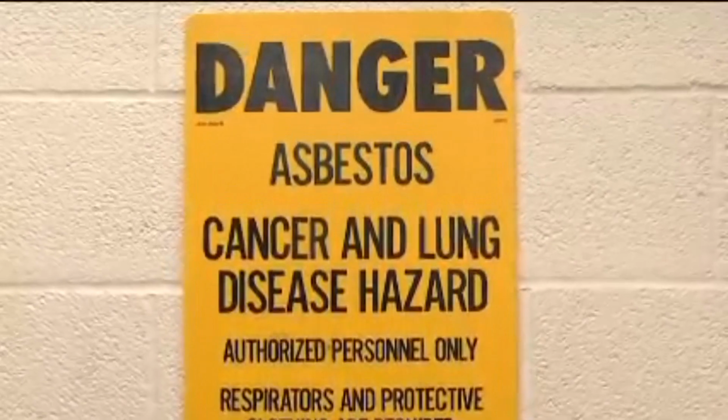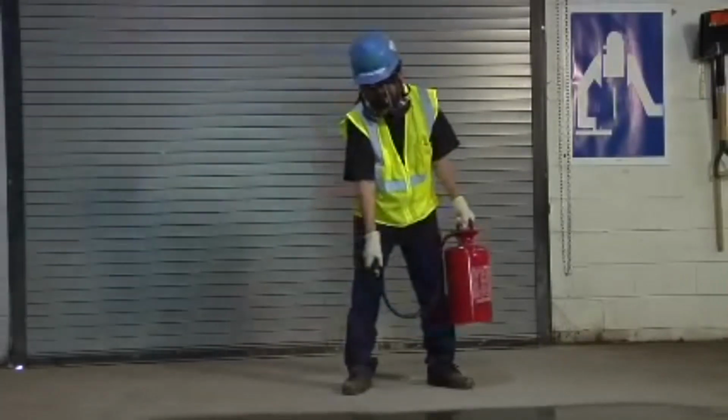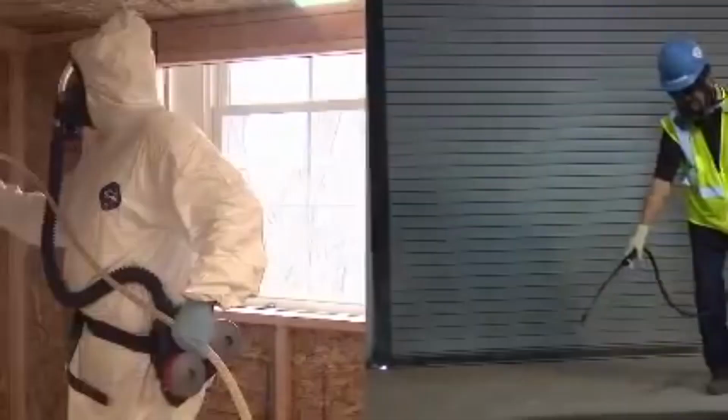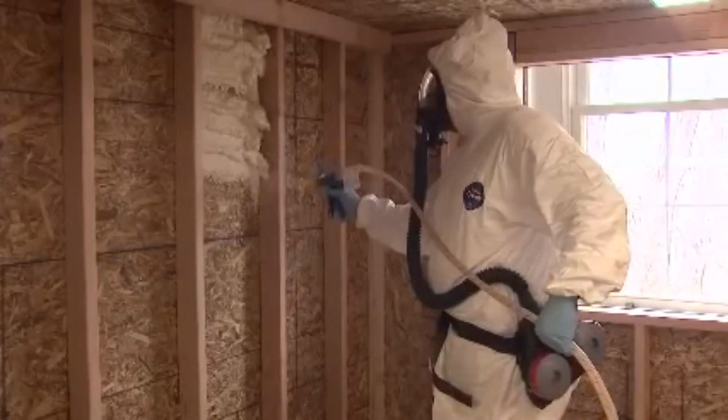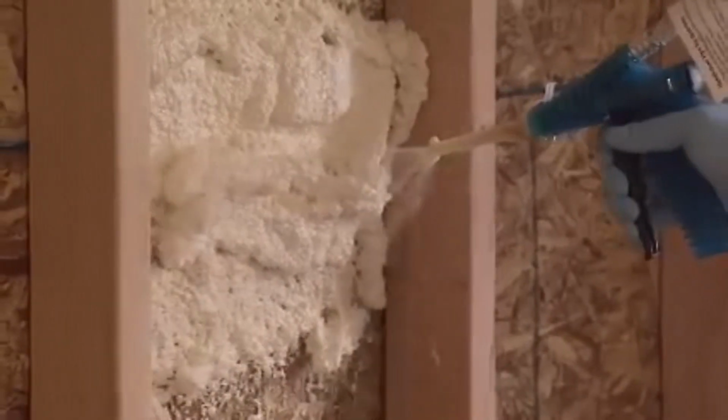More examples of respiratory hazards in construction include lead dust and fumes from grinding, welding, cutting, or brazing surfaces coated with lead-based paint. Silica dust from cutting concrete or sandblasting. Solvent vapors from adhesives, paints, strippers, cleaning solvents, and spray coatings. And isocyanate vapors from spray foam insulation and certain spray paints or coatings.